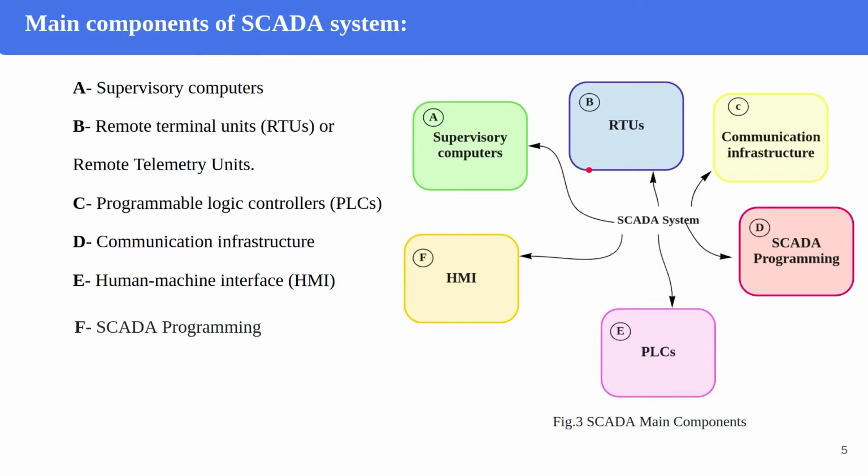Actually, a smaller SCADA system has only a single PC, a personal computer, that serves as the supervisory or master system. But larger SCADA systems have multiple servers, multiple sites, for example, disaster recovery and distributed software applications. So the size of the system is important.